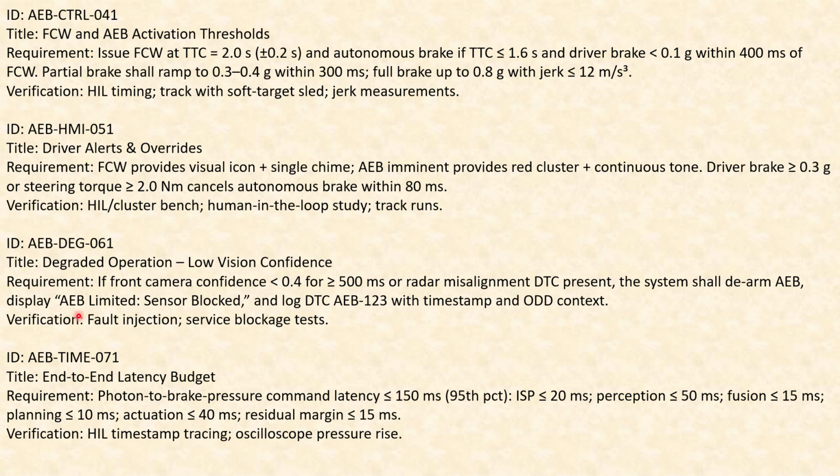All right. So, automatic emergency braking limited, sensor blocked or locked, DTC AEB123 with timestamp and operational design domain context. Again, there is a verification. How do you verify this? By fault injection and service blockage tests.